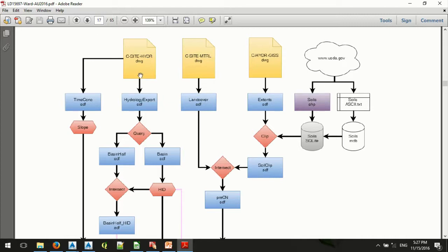So in brief, starting with these AutoCAD files, you use the Map export function to export the geometry as different SDF files. And by the way, this is not optional. You have to export them in SDF, because SDF is Autodesk's custom GIS file format. Out of all the different GIS files you can load into Map 3D, this is by far the most stable one, and is going to keep your system from crashing when you do overlay analysis.